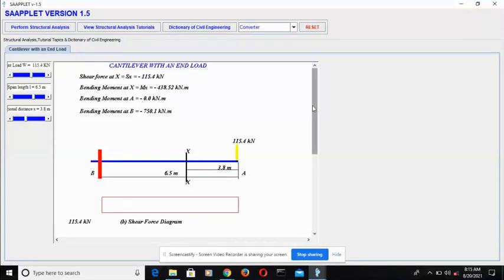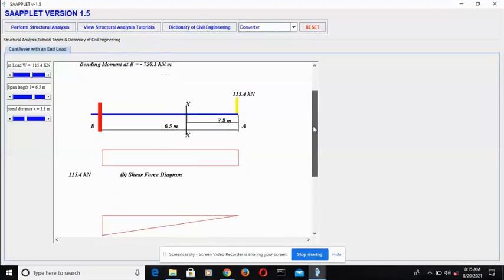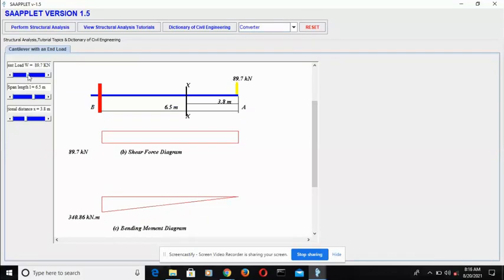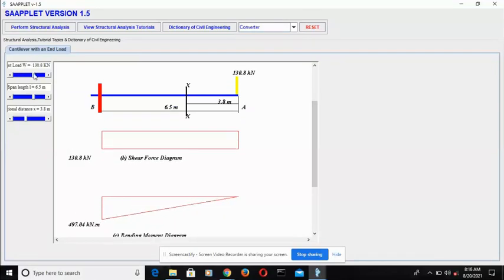changes. So here you can see that the bending moment diagram is being drawn alongside the shear force when the load is being increased or decreased. So it alters the bending moment and the shear force values, while the sectional distance alters the bending moment alone, because the shear force is independent of the cross section or the span, while the bending moment is dependent on the length,